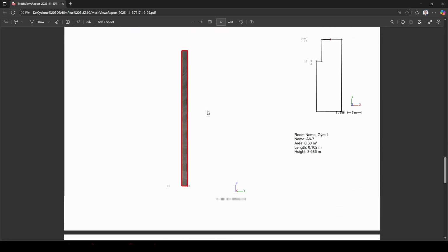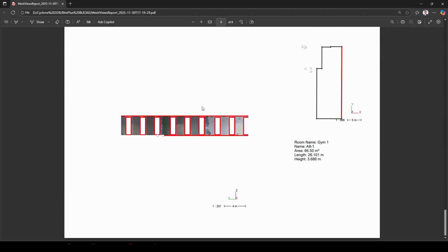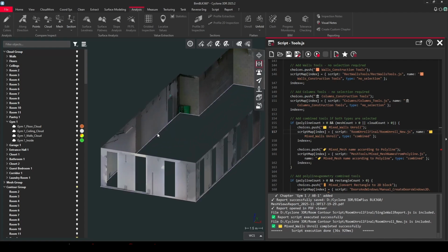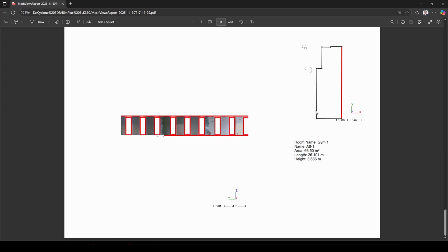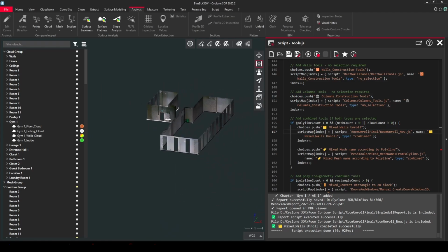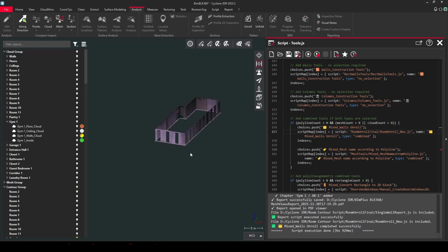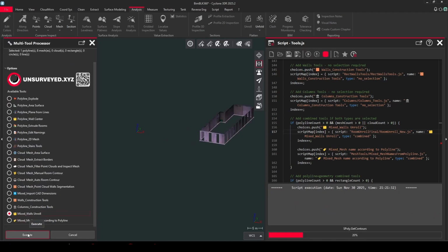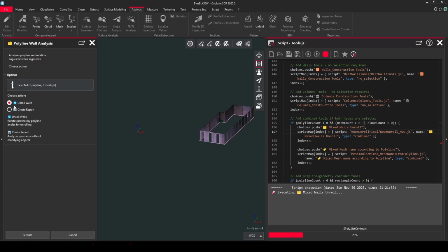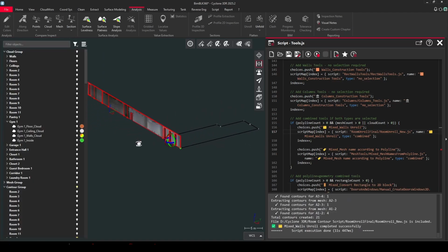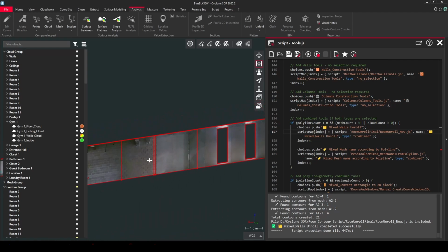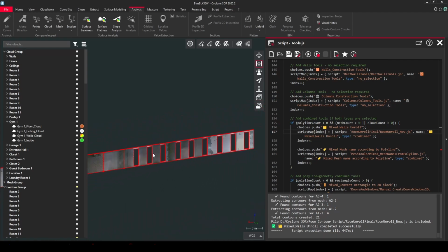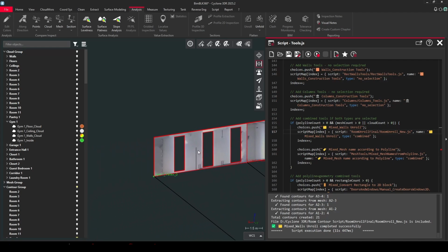These views are generated just as a preview. You can generate better views manually in 3D by using the standard 3D tool. Before running this tool, I recommend you color this line black to be sure that it will be visible here in the top view. And the second option allows you to unfold this: select the mesh and the polyline, run the same tool, walls unroll, and here select unroll walls. In that case, you will see that here directly in 3DR all walls will be unrolled, and you can work with them separately or measure everything manually or generate views manually.